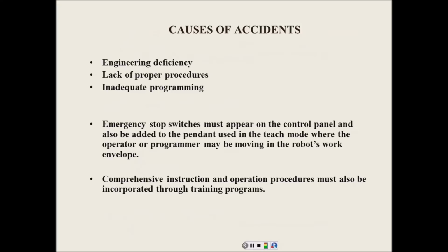So engineering deficiencies and lack of proper procedures give you inadequate programming. Hopefully you won't do inadequate programming. These are programs that are not safe. Emergency stop switches must appear on the control panel and also be added to the pendant, right?